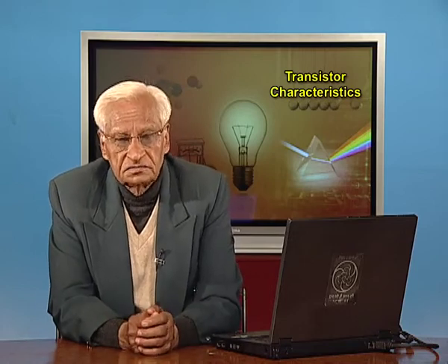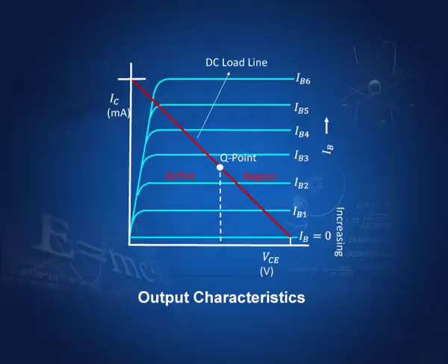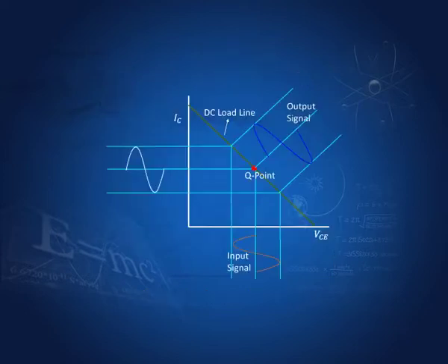for the transistor. But the most important of these operating points is somewhere in the middle, called Q point or quiescent point. Why is it chosen in the middle? I will show you in the next slide. You see, it is chosen in the middle so that the input signal is not distorted. Suppose we had chosen here the operating point, then what would happen? This part will be all right, but this part would be chopped off. So, the input signal would be disturbed.